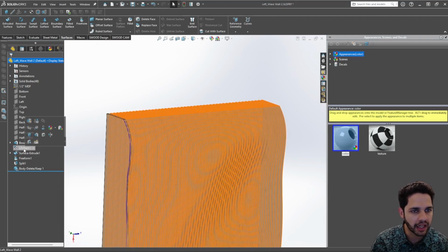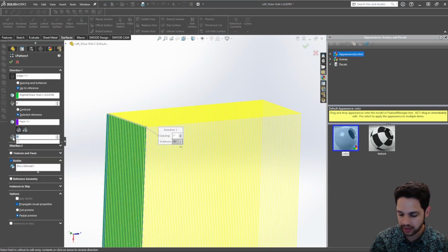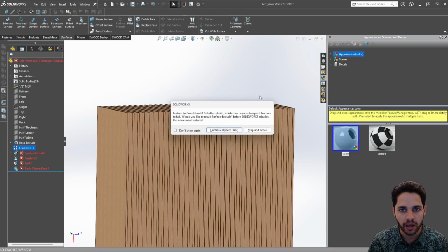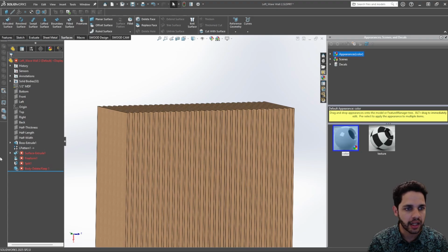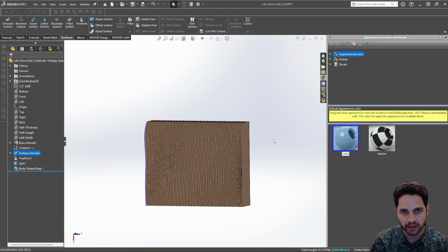And you know what? I think for my linear pattern also, I want to drop this down. Instead of 1 inch, maybe I'll do 1.5, just to keep this a bit more lightweight. And there's probably this issue again that I'm referencing a panel, so I'll select this one here.